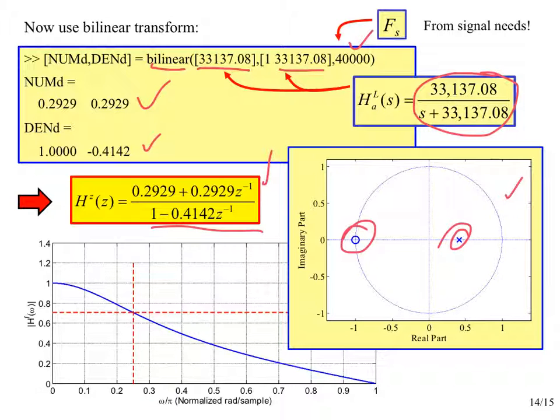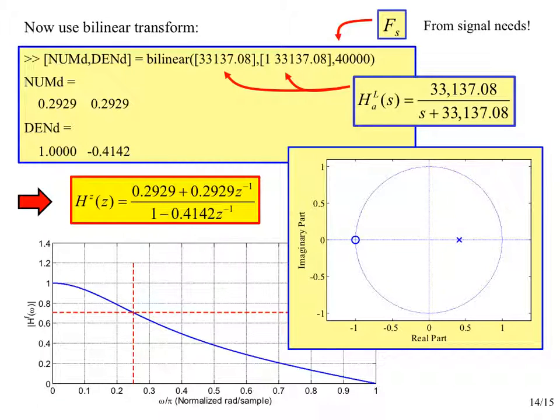So there's our pole zero diagram, and then this plot over here was computed using freqz, using this transfer function. I know that because I see the superscript f there, which tells me that I am looking at a DTFT. And so that's what we have.